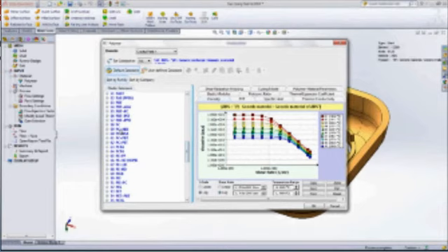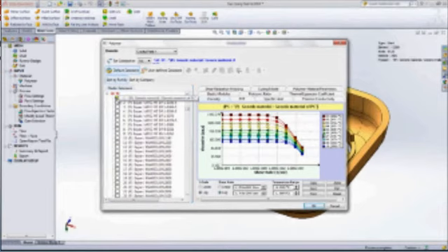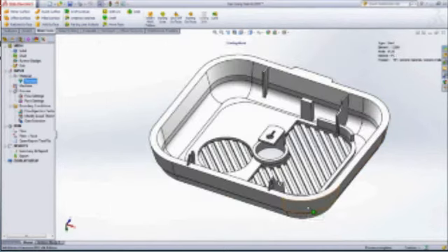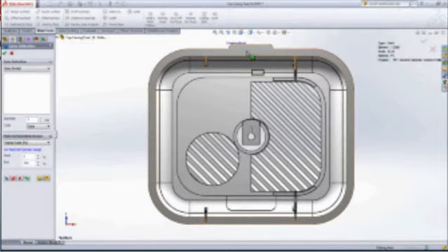Polycarbonate is a very good material with great impact resistance, strength, temperature resistance, and good insulation capabilities. In fact, it's an excellent potential candidate for this particular application. The last step before running the analysis is to specify the gate location or injection location. Let's just pick an edge gate at this point.